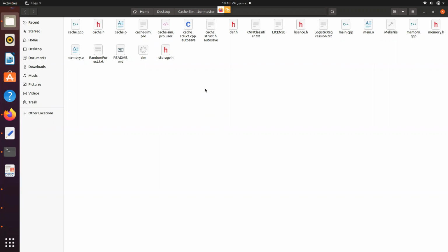Now we analyze the test results of cache performance by monitoring the access count, fetch count, prefetch count, hit rate, miss rate, and average access time on both L1 and L2 cache. We consider three replacement policies: LRU, PLRU, and random.